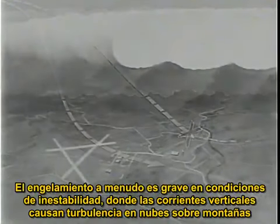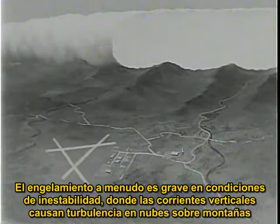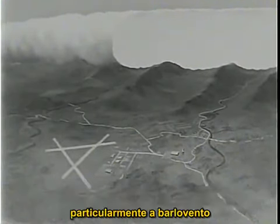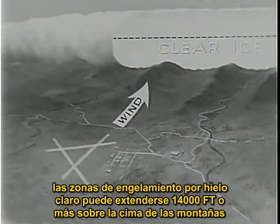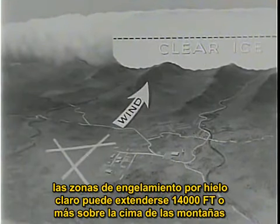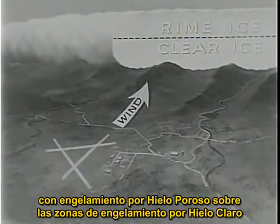Icing is often severe in upslope conditions where vertical air currents cause turbulence in clouds above mountains, particularly on the windward side. Regions of clear icing may extend 4,000 feet or higher above the tops of the mountains, with rime icing above the area of clear icing.